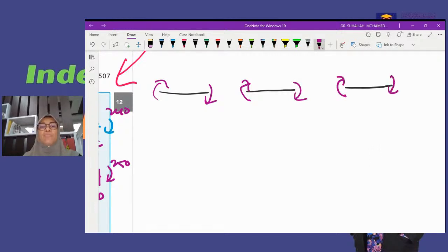This is member end moment. And beside the member, we have the joint. Okay, we have joint here, and then we have joint, fix. And the concept is joint moment is always opposite with member end moment.